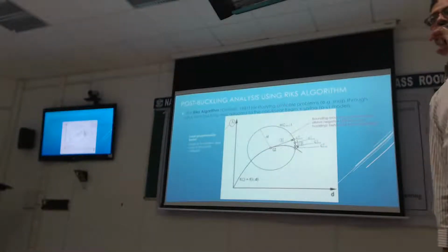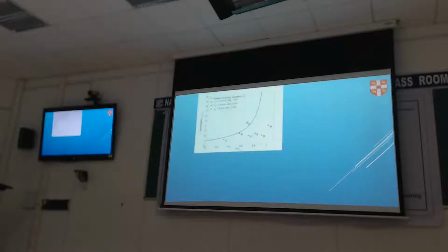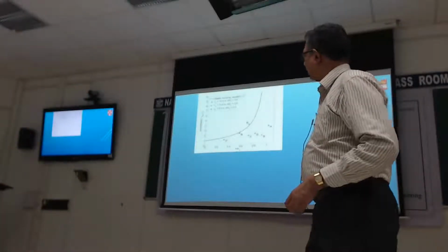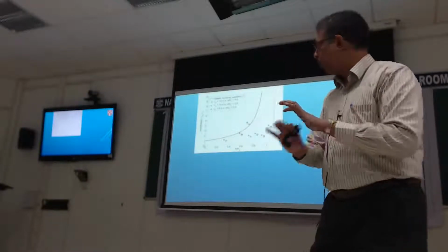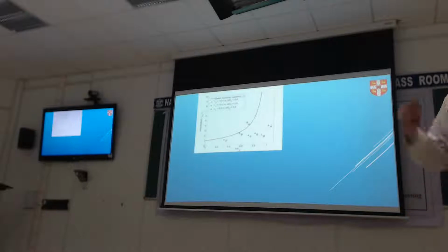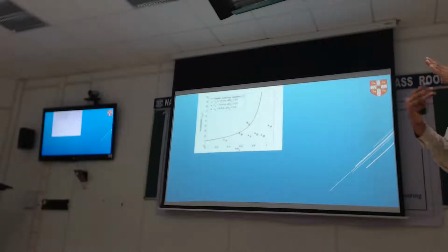Now we are in a position to have a numerical go at what we have been observing in the experimental results. Let's see if we took all the experimental evidence we have and plotted on the y-axis the amplification, if you like. That is the displacement I'm going to get because of my earthquake at the pile head compared to the displacement I'm going to get because of buckling.